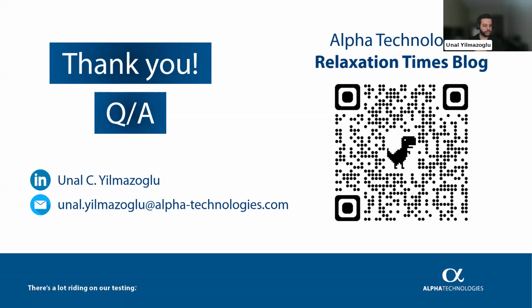Yeah, for the compound shelf life, I think this question addresses the aging case study that I showed lately, where you could perform an aging study to assess the shelf life. And for extension, basically the RPA is a shear rheometer. It does not operate in extension, but in past papers we proved that there is a linear correlation, with a coefficient of R squared 0.99, with the tensile testing. So as long as you create that correlation chart, you don't need to run extension tests anymore. But again, the RPA is just a shear rheometer, not an extension rheometer.